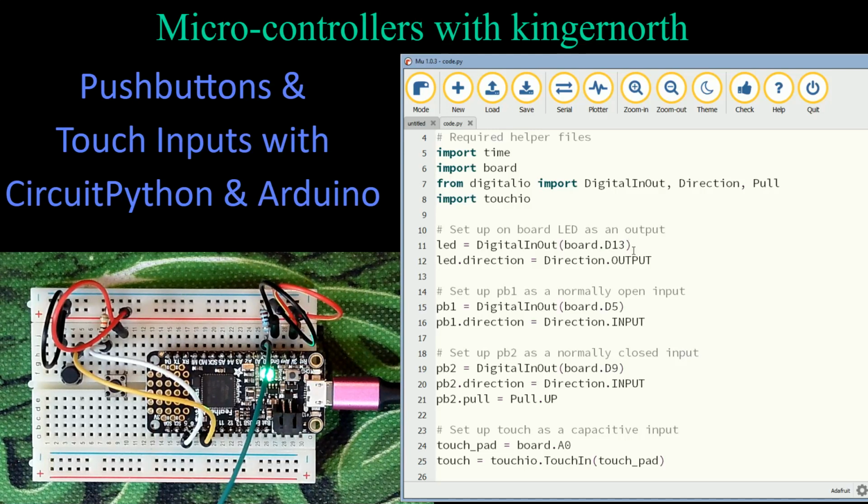And that's exactly what it's doing. The next line says LED is the variable, set the direction. So we're going to set the direction variable within LED now to direction as an output. That's it. It was no different than putting in pin mode in the setup file. So this was pin assignment and then the direction, what we want to do with it.